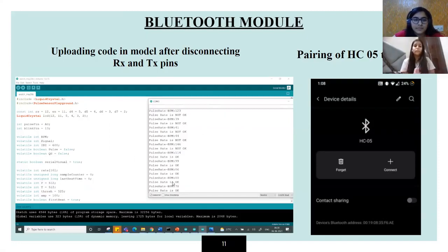Also, we uploaded the code to the module after disconnecting the RX and TX pins. As we know, the RX and TX pins of the Arduino board are busy, so we have to disconnect them first and then upload the Bluetooth code to the system, so that it does not give an error. So we have successfully uploaded the Bluetooth code to our system.